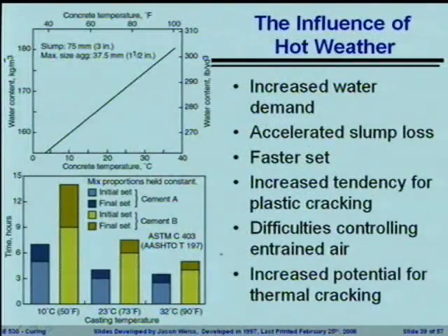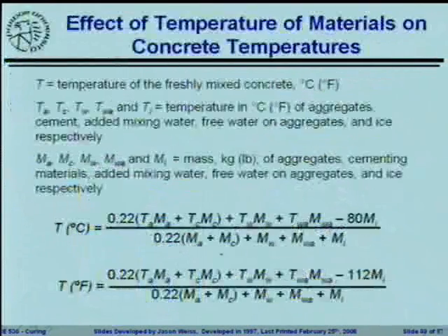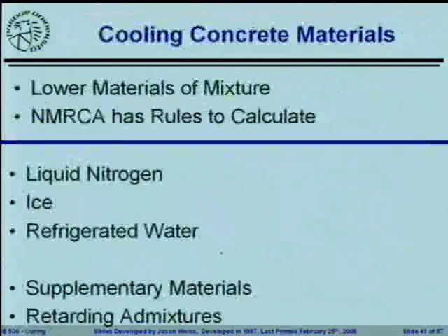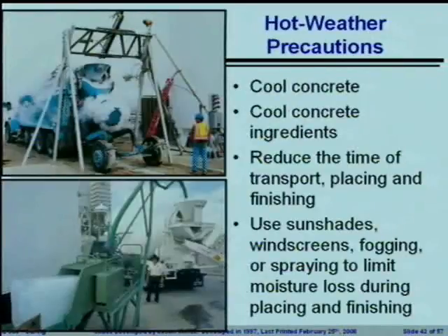Obviously, the hotter the temperature, the faster it's going to set. One of the things that you can do is figure out ways, if the concrete itself is too hot, to cool down the initial ingredients. Here you can see cases where they are replacing liquid water with a different phase of water, this ice. They're making the concrete a great big icy or slurpy, depending upon your particular interest.